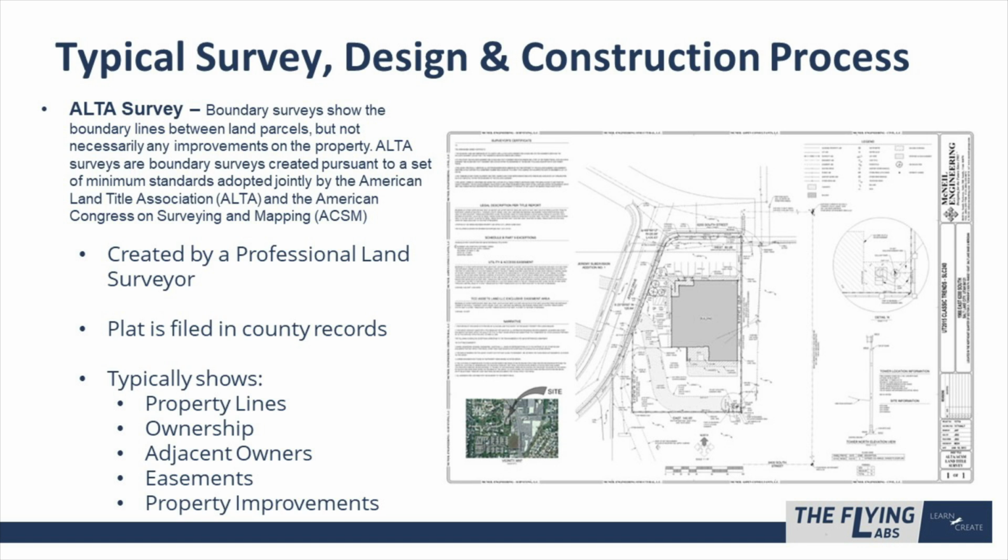So it's a set of standards as to how these plats and these ALTA surveys are documented and what goes on them. Like I said, they show property lines, ownership, and adjacent owners, and again, they're done by a professional surveyor. It's required to be signed and sealed accordingly.